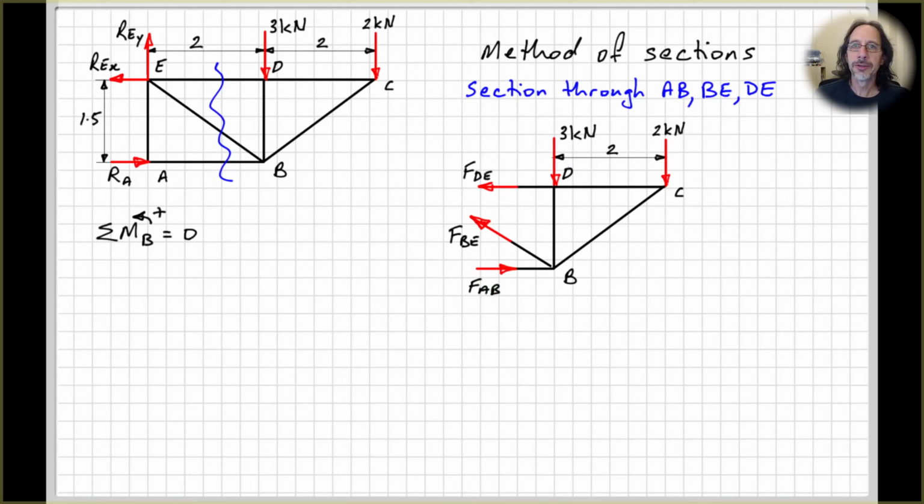All right, so let's start applying our equation of equilibrium, and as we discussed, the place to take moments about is point B. And remember that you must indicate on your equations where it is you're taking moments about. So here, this one's going to be pretty simple. But before we do that, let's put some dimensions on our free body diagram.